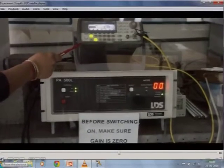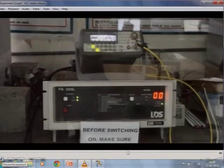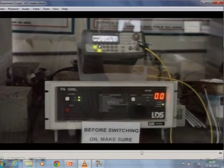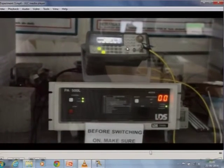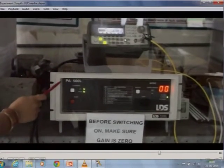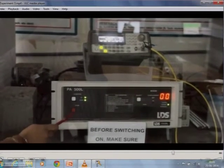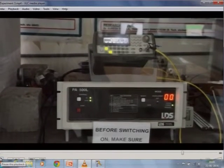This is the function generator which produces the electrical signal in the form of a sine wave, and we have adjusted the sine wave frequency in a sweep form using this function generator. This electrical signal is transferred to this amplifier, which amplifies the signal and then finally transfers it to the shaker. The shaker then converts that electrical signal to a mechanical signal in the form of force.